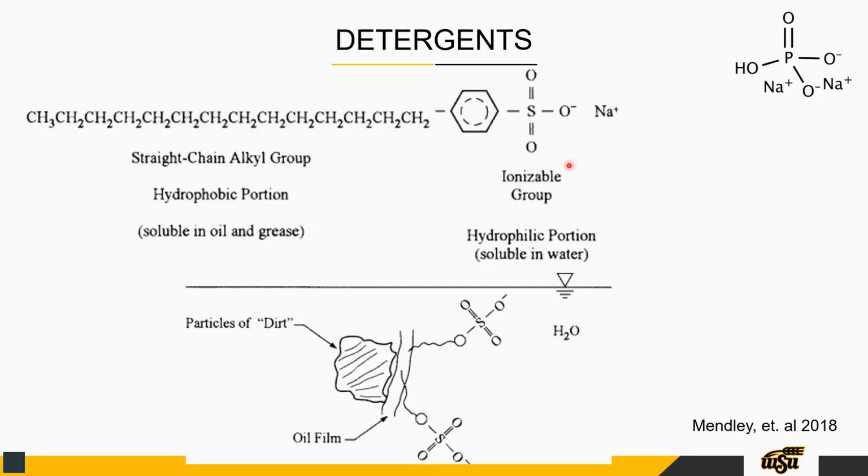If there's a lot of these type of detergent molecules in your water, you will typically get a less efficient reaction because some of the chemical that you're applying to remove this is actually going to be interacting with these particles. A chemical can only react with a chemical, and then it will be used up. So if you interact with this, bind it, then this orthophosphate will still be floating around in solution.